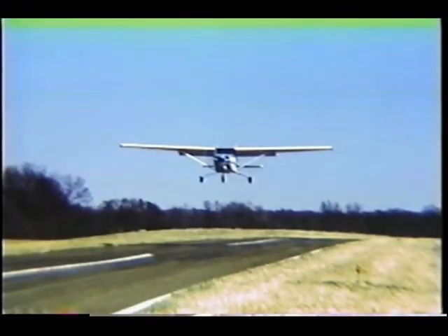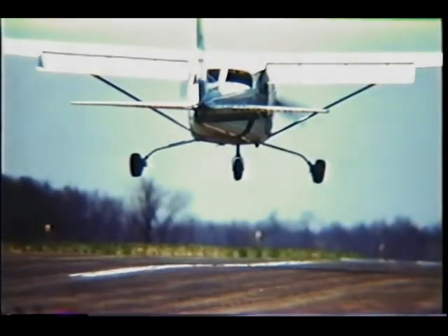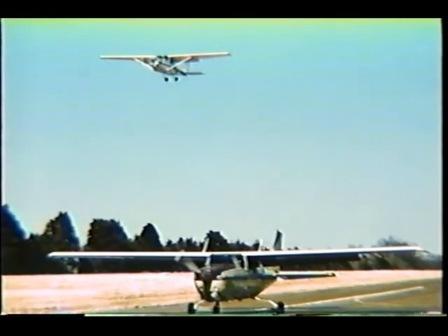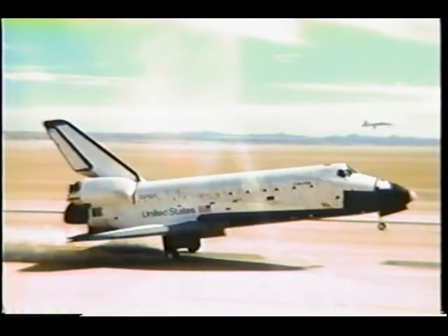That's right, do it. And once you've made your decision, stick to it. Don't vacillate. Even if it begins to look like you might be able to make it after all, stick to your decision. Take it around. You have an advantage that space shuttle pilots don't, so why not use it? Too many airplanes have been lost because the pilot changed his mind back again and tried to land after all.